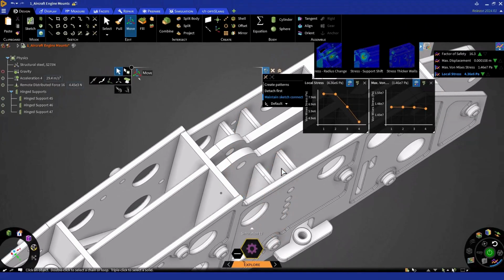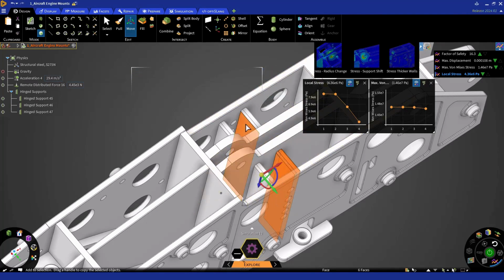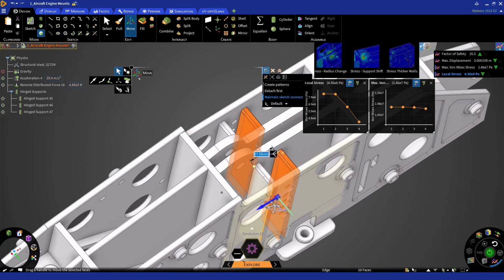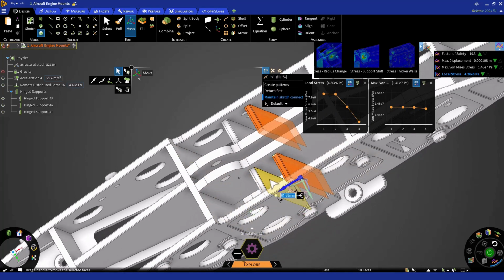Now, let's select the two new walls and drag the local Move coordinate system towards the forward face of one of the new walls. This will ensure that we measure from this face to the reference point. Now, click on the arrow pointing forward and then on the ruler. You can now select the reference point. We'll select the closest face on the original wall. We can now specify this measurement, which will be 65 mm in our case.